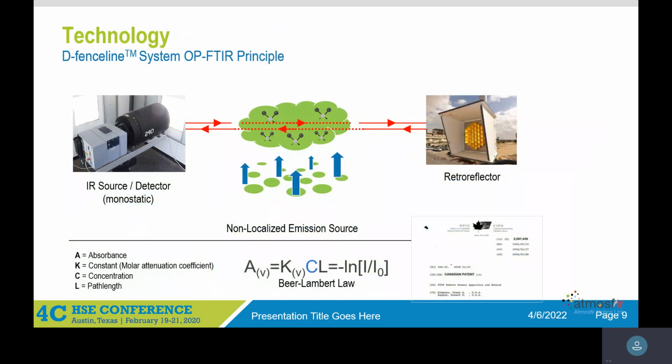A little bit about the open path technology. What we can see here is an open path FTIR. We use the Bruker FTIR just because it's the fastest scanning, the highest resolution, and has the lowest noise, the best signal to noise ratio, and that gives us the ability to give the best detection limit, and it's also robust. This is a $6.5 billion company, while the rest of the manufacturers are usually small.